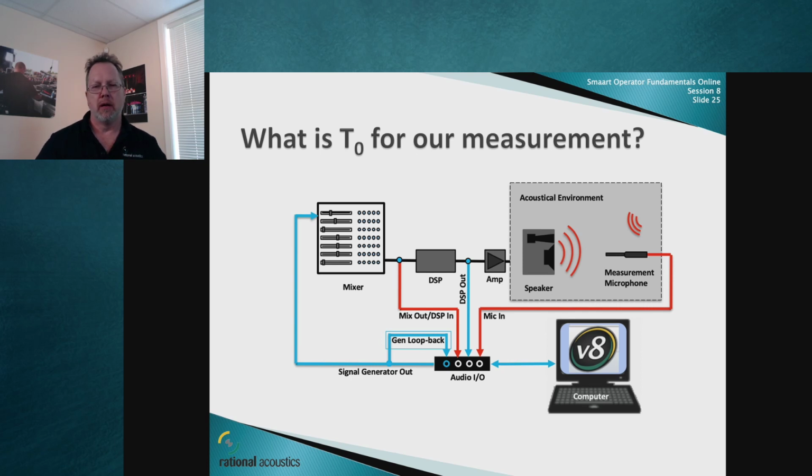Just remember: lagging, on time, leading. Left to right, downward is lagging energy, horizontal is on time. Now it doesn't have to be a horizontal slope at 0 degrees. It has nothing to do with the degrees on the side of the plot. When you go from a downward slope to an upward slope, that inflection point is the zero point. That's what you're timed to in your measurement. What's going up is arriving early, down is late. So that's one of the keys to reading a phase trace.